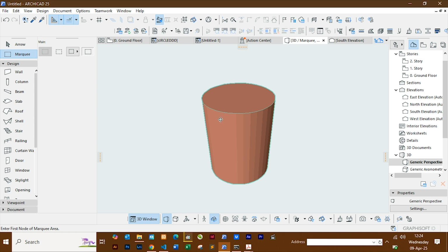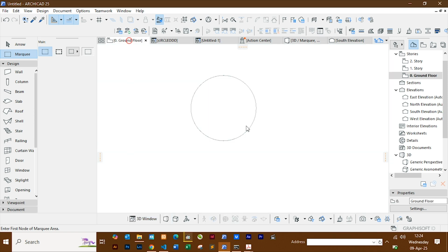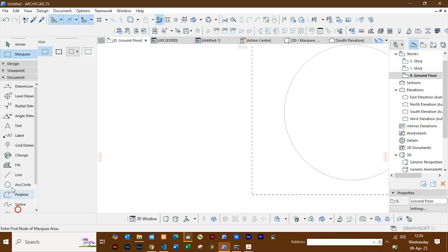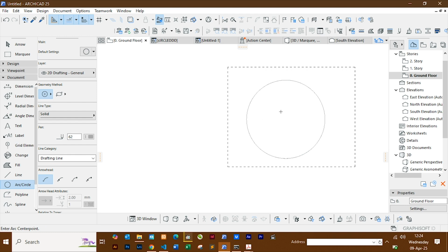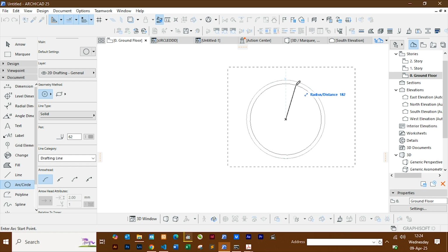Now we want to make a pipe out of this. So it means go back to the slab. We now draw a circle inside our circle here, inside our creation. Look for the center. Remember the other one had a radius of 200. Make this one smaller. Let's say the thickness of our pipe is 10. So that means 200 minus 10, we make it 190.